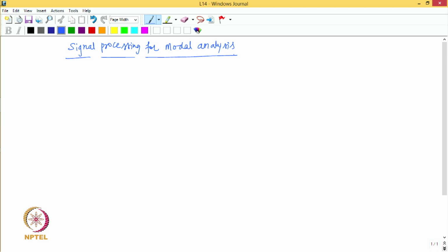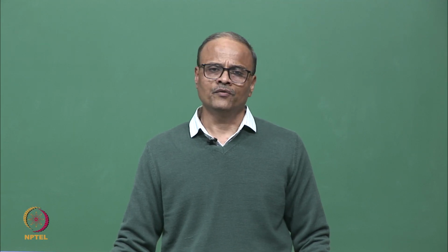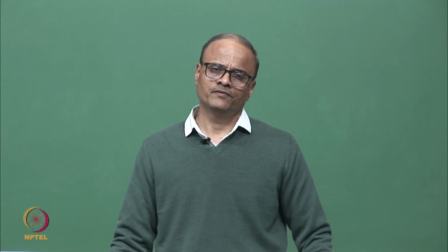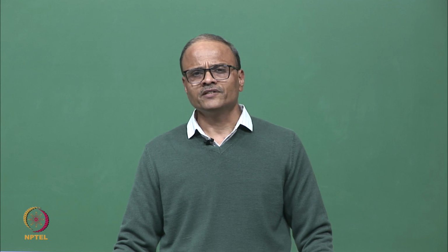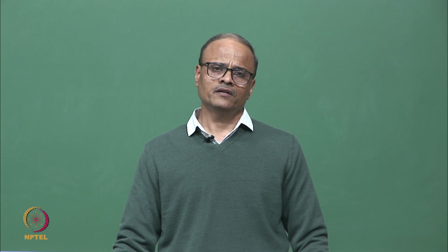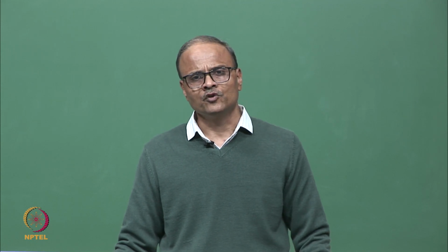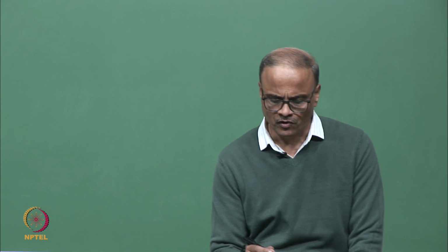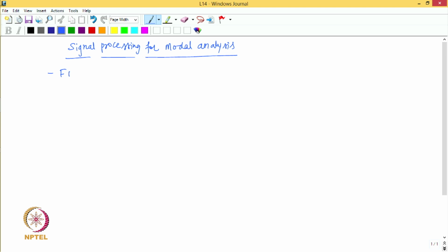So, for experimental modal analysis, FRFs are basically the fundamental inputs which are processed in order to obtain the modal parameters of the system. And FRFs we have defined earlier as the ratio of the response and the force in the frequency domain. What we measure are the response and force signals, which are nothing but time domain signals, and these need to be transformed to the frequency domain to find the FRF. So, that is one motivation for signal processing, FRF estimation.